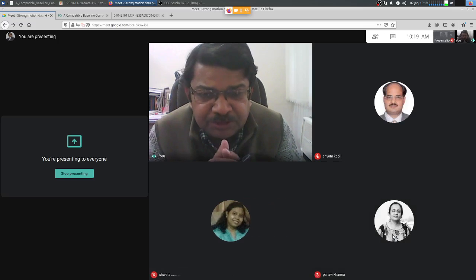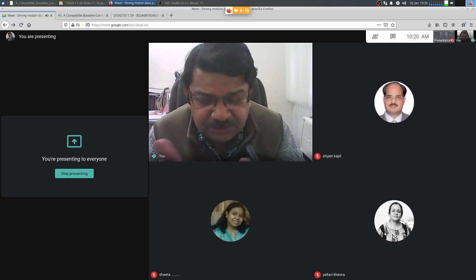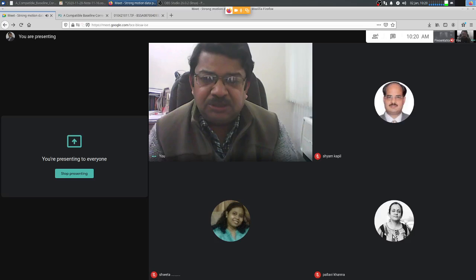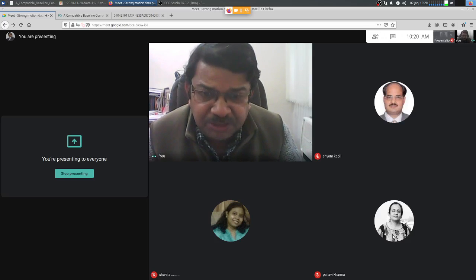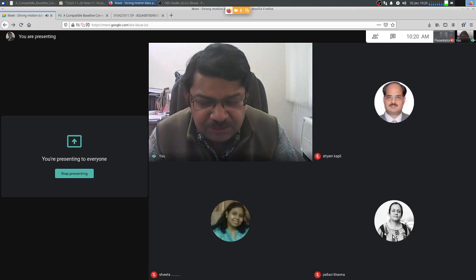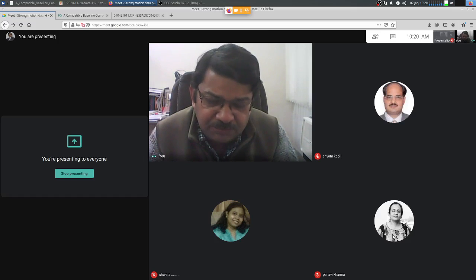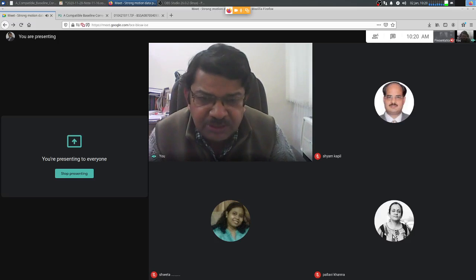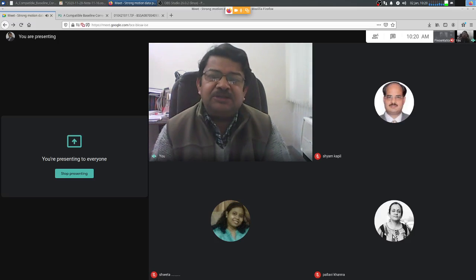So it was possible to have a programmable setting for pre-event time, that means the total length of the record which will be preserved before the instrument was triggered, and post-event time as well, after the base acceleration fell below the threshold. Then how long the instrument should keep on recording the motion would be appended to the triggered section of the record.